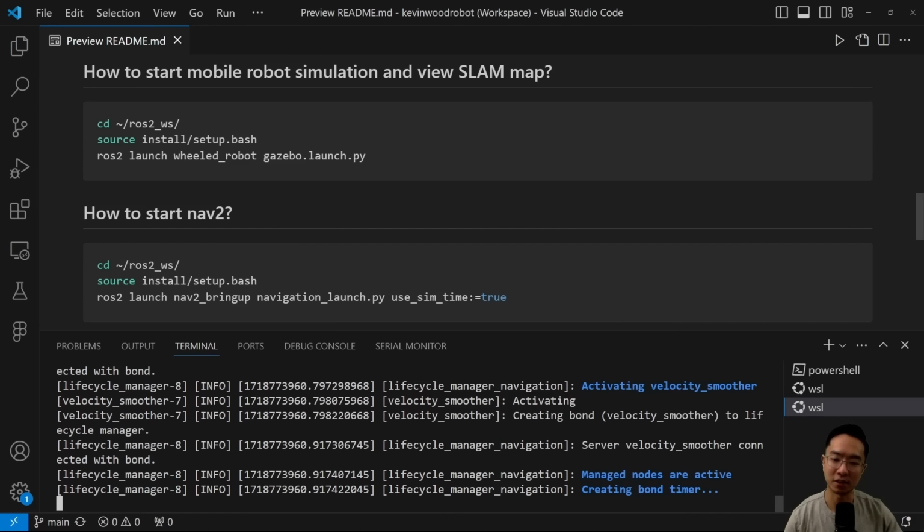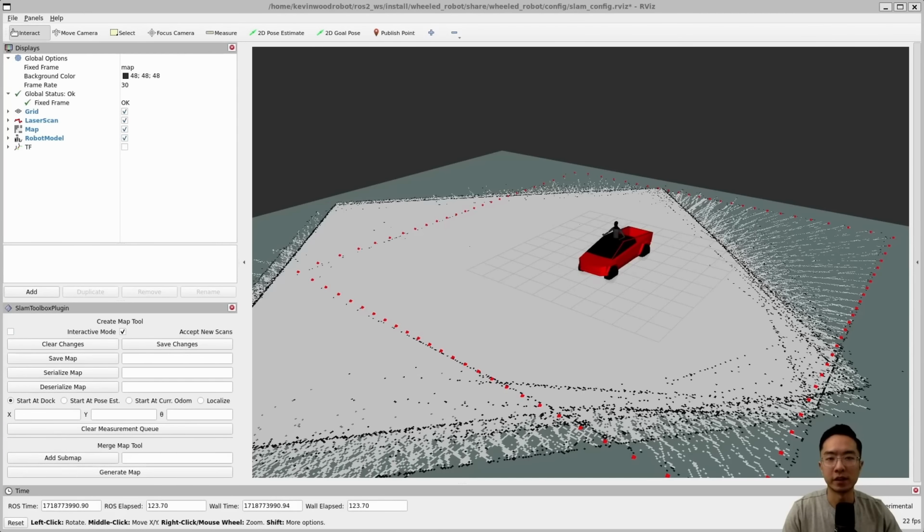But to actually see the cost map, you need to make sure that we run this launch file. What this does is tie some of the commands together to our actual robot, which we'll see later on when we're trying to navigate it. Right now we see our typical map, but what we're going to go over now is how to see the cost map in Rviz.